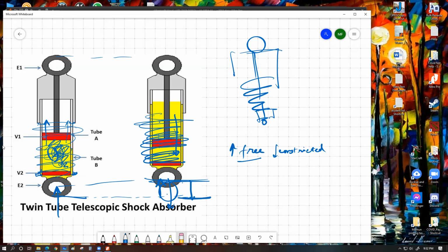This type of systems are what we call over-damped systems, which absorb the energy within itself immediately and release the energy over a duration of time, that as a result, the oscillation cannot continue. We are taking out the oscillation energy within the valve system, and then we are slowly going to release this energy later on, which is going to give us an overdamped situation.